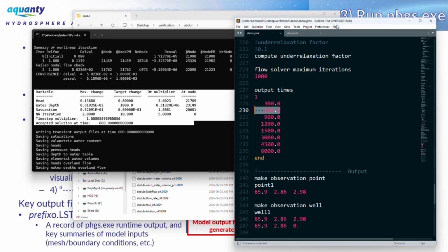If your simulation is 100 days long and you're taking 1 day time steps all along the way, then it will by definition require 100 time steps. But if your simulation can go from a 1 day time step, to a 2 day time step, to a 4 day time step, to a 10 day time step, you might be able to solve the entire system of 100 days in maybe 10 time steps as opposed to 100. So that's going to be a lot faster.